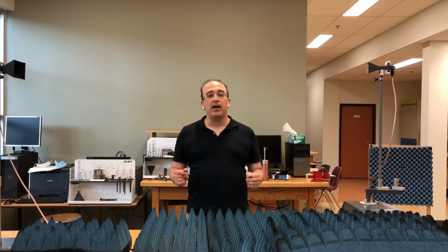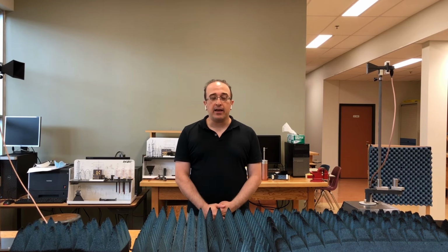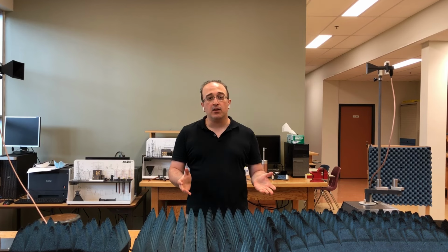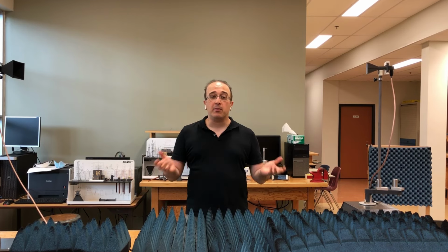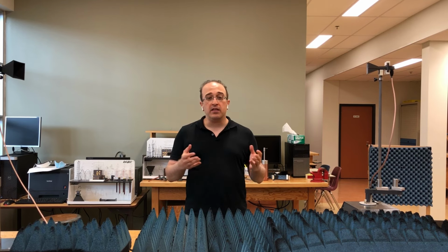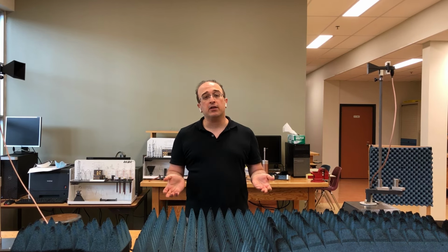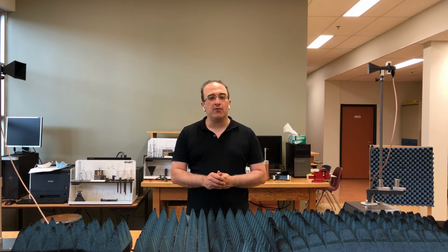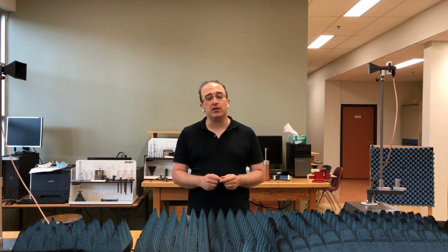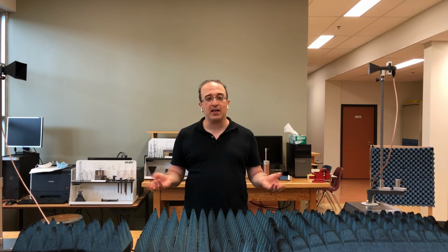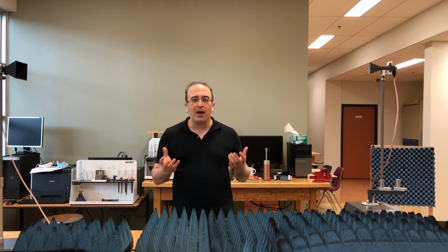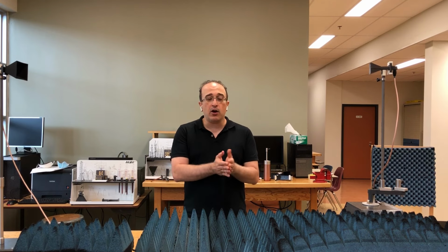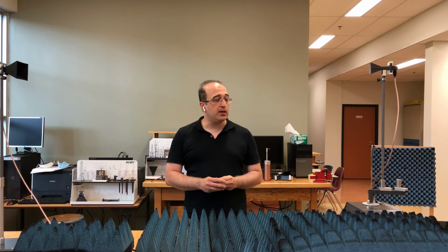Okay, now that we have measured the E plane and H plane of series fed patch array and parallel fed patch array, and we have the maximum signal level of these two antennas, it's good to also calculate their gain, because right now we only have maximum signal level, which depends on different situations. For example, what is the distance between transmit and receive antenna? So maximum signal level by itself is not very useful, but if we can convert that number to gain, that would be very useful for us.